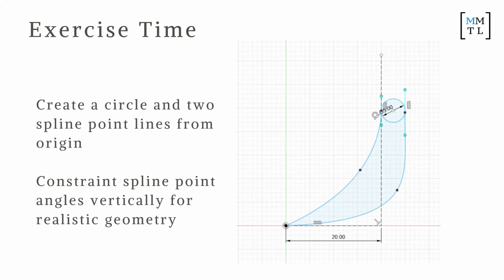All right, so now think about which plane we're going to create this sketch on to make a 3D shape that we can view in Fusion 360 nicely. You wouldn't want to sketch on the XY plane anymore, right? Because then when you revolve, it's going to be going into the ground. So you want to sketch on the ZX or ZY, yeah, ZX, right? That's probably what we want to sketch.